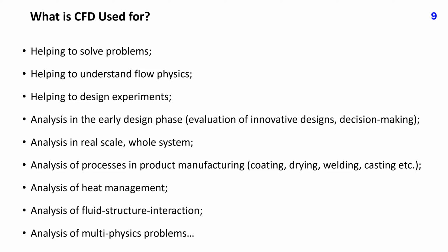CFD is an invaluable tool for flow analysis in an early design stage or to evaluate the ideas of innovative designs for which no past experience exists. Knowledge acquired before any prototype is built is a competitive advantage. Changing designs in later stages becomes very expensive as this may require many system changes. CFD allows an analysis of interaction of various system components. It is not enough to design an optimal hull, propeller or rudder alone, assuming ideal flat water surface.